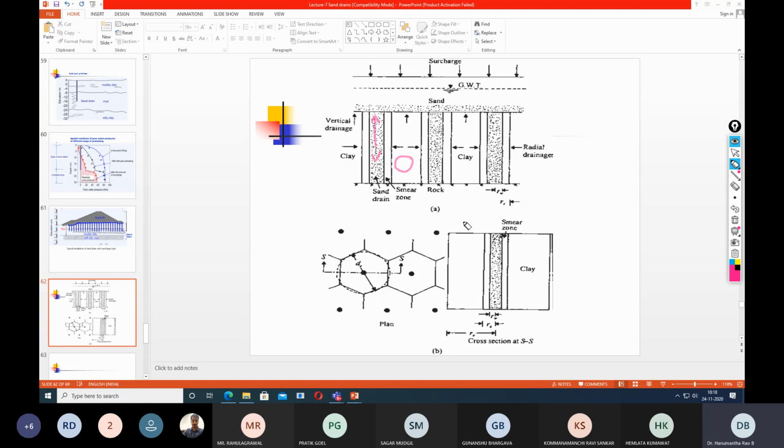In the case of pile foundations, we can do a pile integrity test to check whether the pile is vertical or not. In the case of sand drains, I don't have any idea. The only thing is, if it doesn't work, then we should ascertain that there was some problem in the sand drain. It is really difficult. It's not so easy.